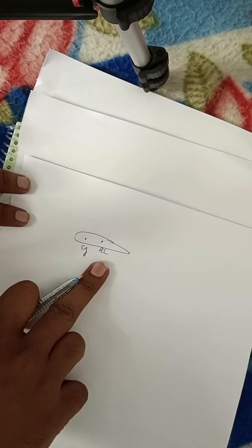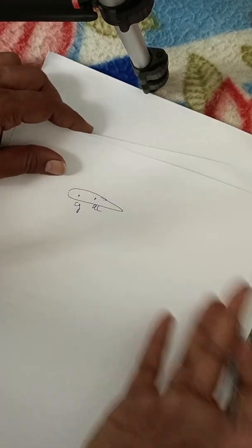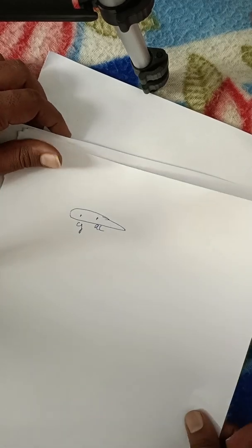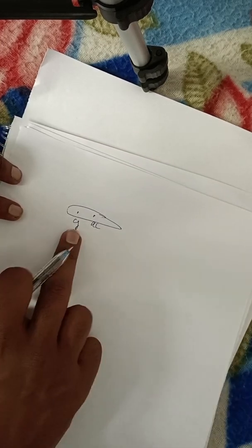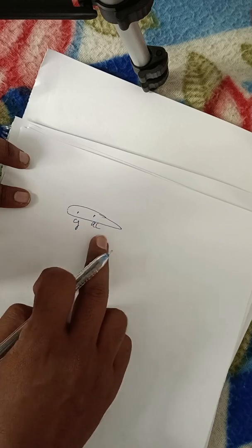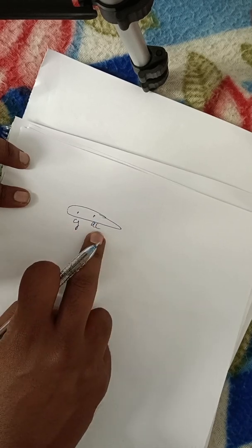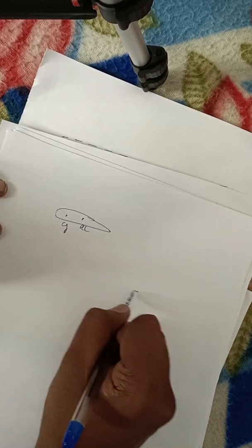This is what we have learnt in the last derivation. What's the contribution of the wing? If the CG point is forward of the AC point, it is stable. If the CG point is behind the AC point, it's unstable. So if I want to make any lifting surface a stabilizing surface, I should place the CG point forward of my AC point.